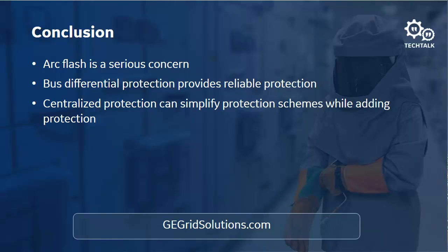Depending on the space layout that you have, how long the runs are, because the optical sensors do have length limitations. You could have it in a different location. But again, if you move a relay like that, it's not just the light sensors being moved, it's also going to be the CT cables, all your control cables are going to be remotely located.